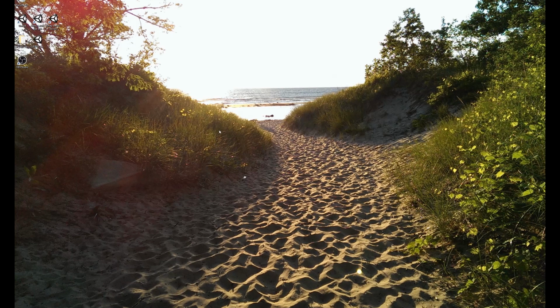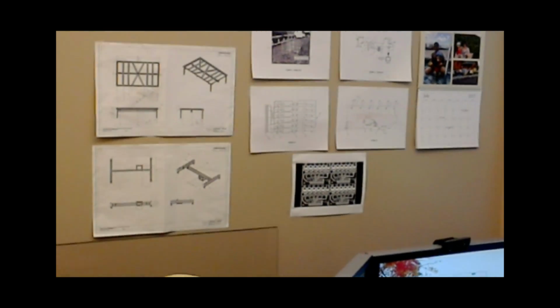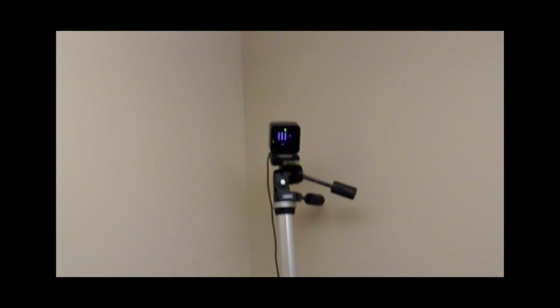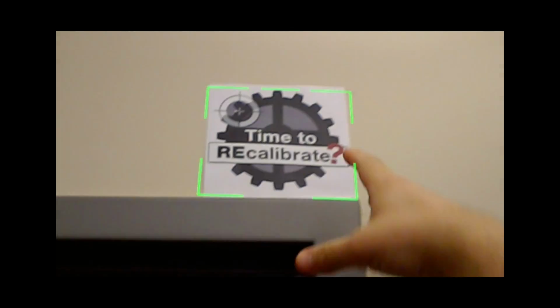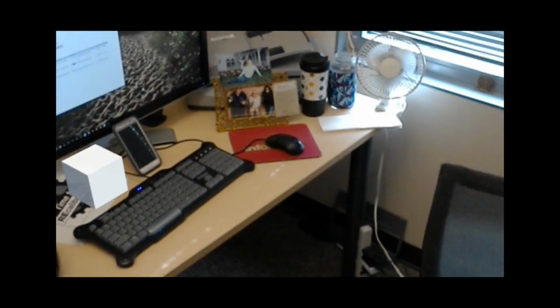So I'm going to do that right now with the HoloLens. What's happening here is I have my office space that I've scanned and I want to put a cube on my desk over here. So I have this target up on the door and this acts like a calibration target. Anytime my 3D graphics get mixed up or not quite calibrated to the room from my Unity project, I can just look up at this and pay attention until these green lines line back up with this image target. And all I'm doing in this app very simply is putting a cube on my desk, and that's it.